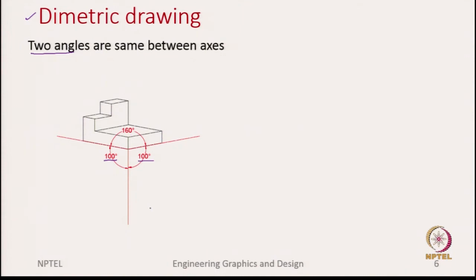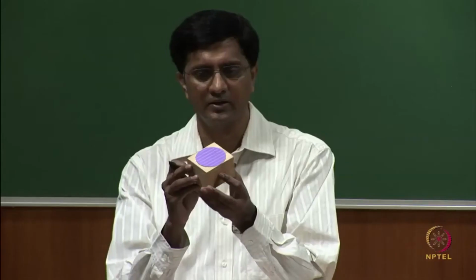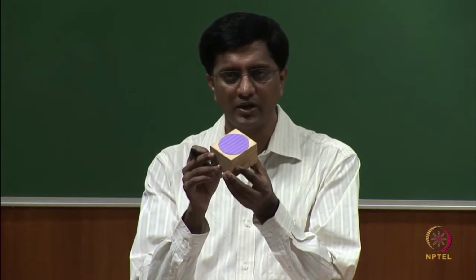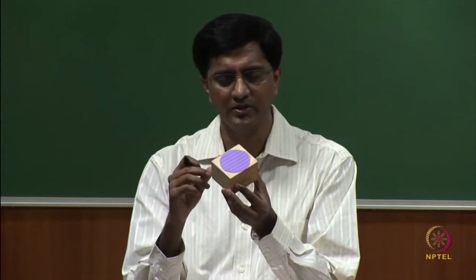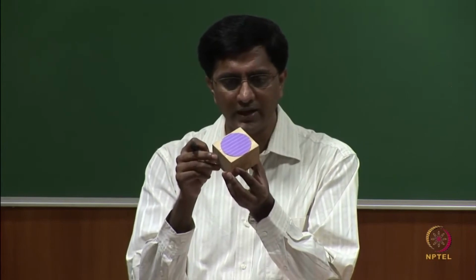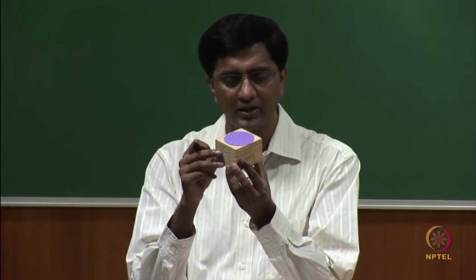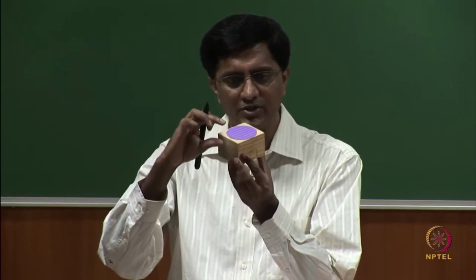As you can see, let us say the front face and the side face both have the same dimension, whereas the height is slightly squeezed. The difference I will explain. Previously we were working with isometric, where all three lengths are equally proportional, but now I tilt it in a way that the height dimension is squeezed.